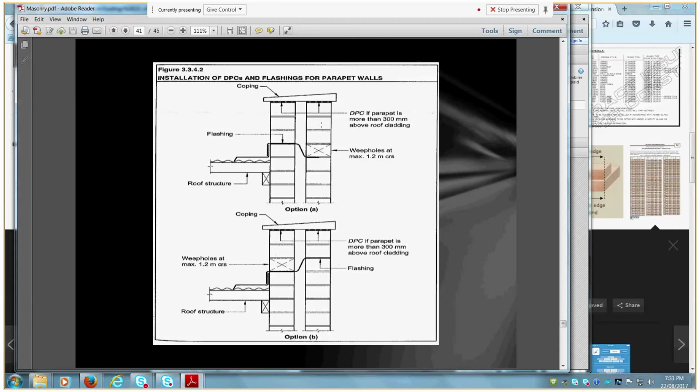That causes aesthetic issues, in that you typically get black mould happening, primarily on rendered surfaces, but also on brickwork. There, you get unsightly marks from that moisture if you're getting a decent amount of moisture coming through here. Whereas with this detail, if you get moisture coming through the cavity into your parapet wall, it's carried out onto the roof. So, of course, flashings must always overlap against the direction of the flow of water. So you have to think about that.